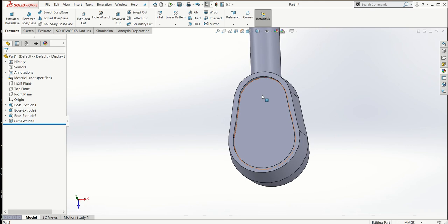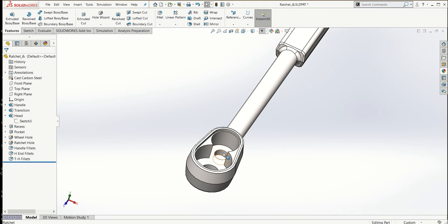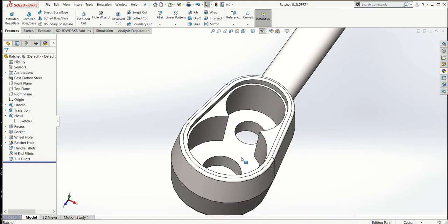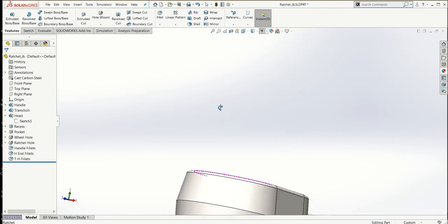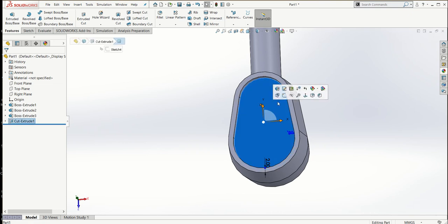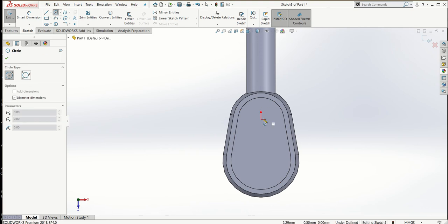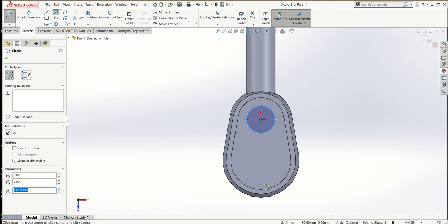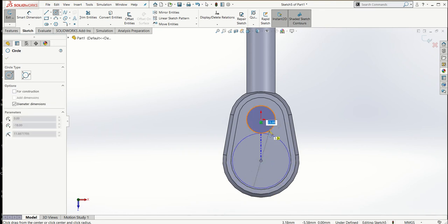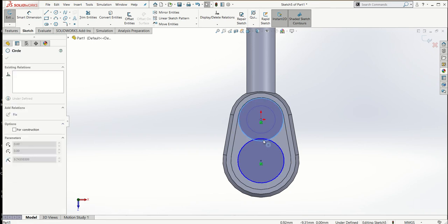Now, if you see here, I want these two circular cut extrudes inside that body up to a particular distance, not through. And if you see, the radii are 9 and 12. So for that, control tab. What I need to do is again select the sketch. Okay, now I will draw a random sketch here. I know the circle is fixed. Now I want to draw a circle here, so I will select this and just randomly click. Okay, now I will make a bigger one.